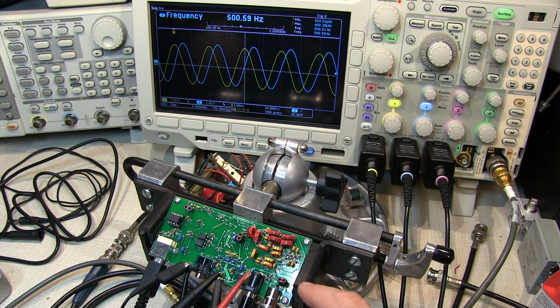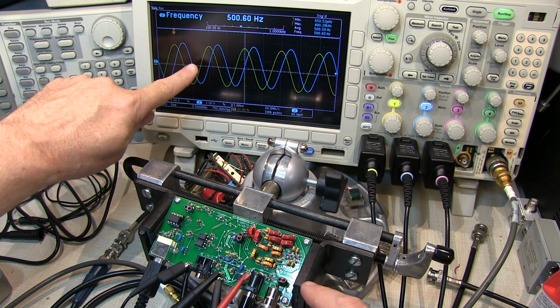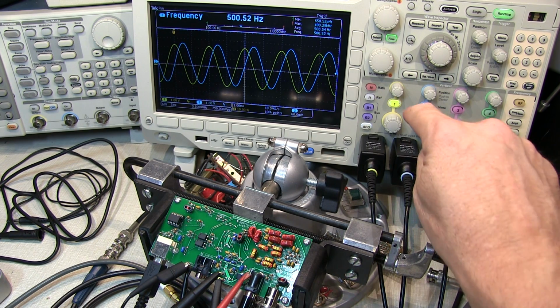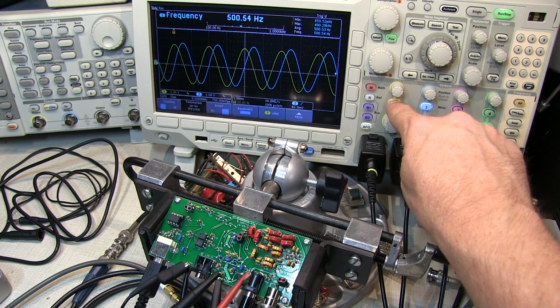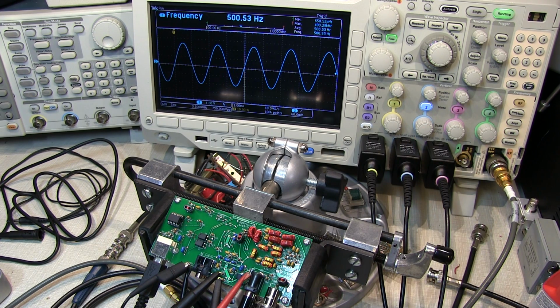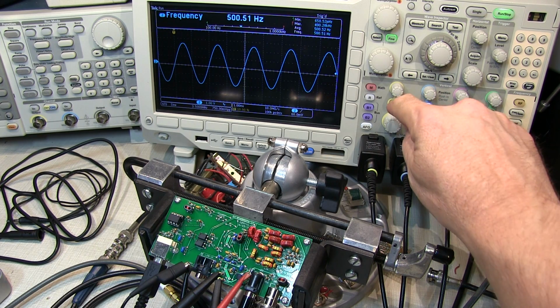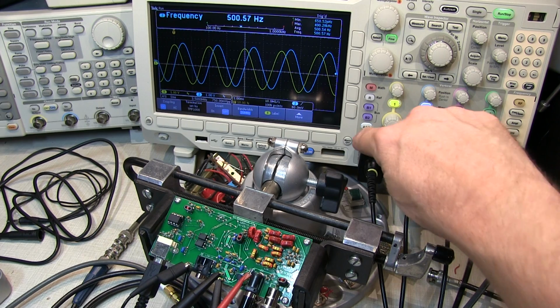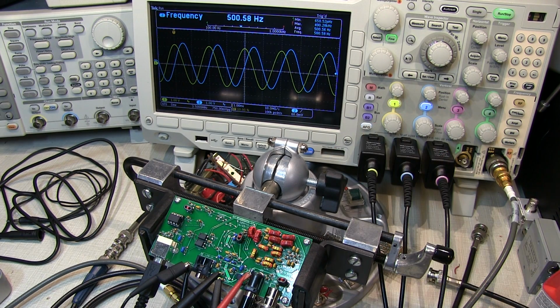As a result, what we see are 2 sinusoids, each at the same frequency, about 500 Hertz, and 90 degrees offset from each other. This is what you would expect to see on a direct conversion receiver with a 500 Hertz offset at the input: just your 500 Hertz tone, and that's often what you'd use to listen for CW. In an SDR receiver, we use Quadrature outputs, get the I and the Q, and that's shown here with these guys 90 degrees out of phase.